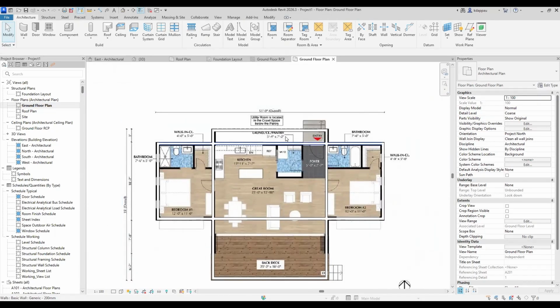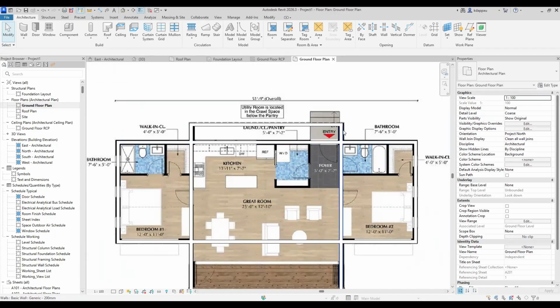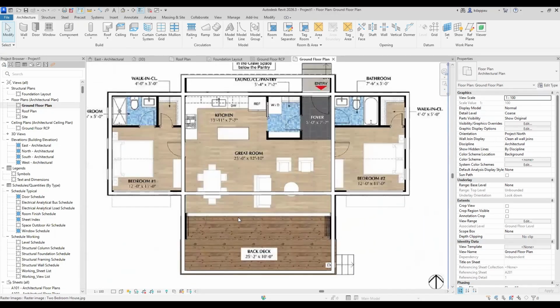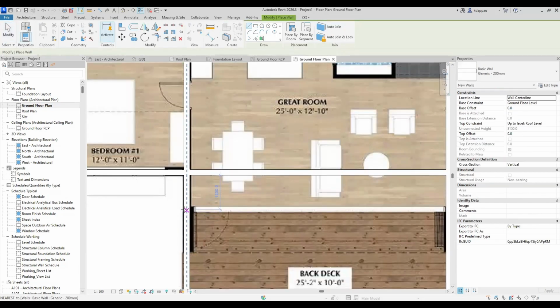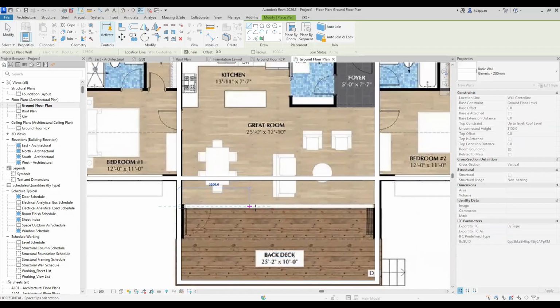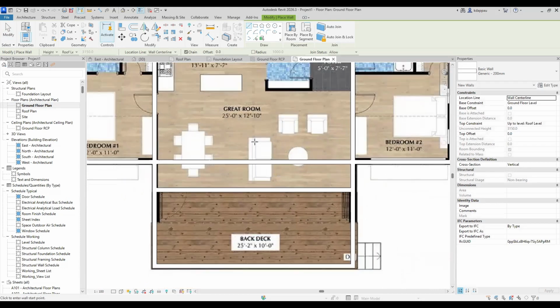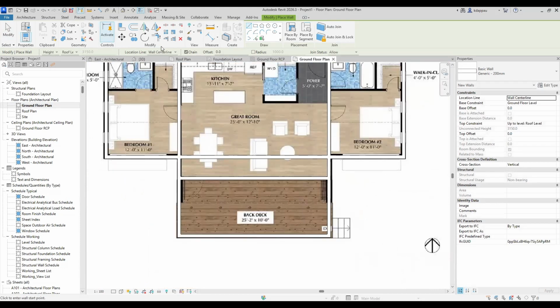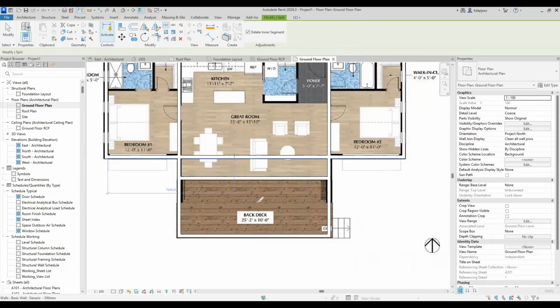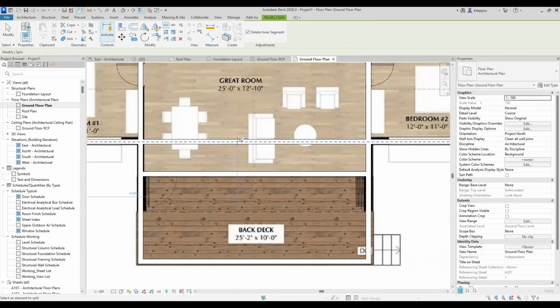So what I'll do is, this balcony is okay, it's just the entrance terrace, but this wall here cannot go all the way to there, it should rather be moved to this location here. So I'll pick another wall from this corner here to come and meet that corner up to this point. Then I will use the split tool. This modification tool, there are many of them. Try using them. If you get any challenge with any of them, let me know. So I'll use the split tool here and then split this wall here.